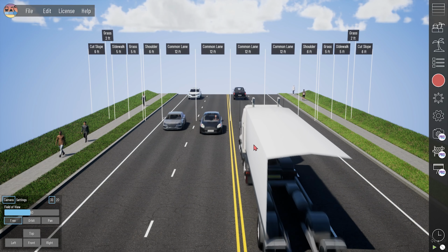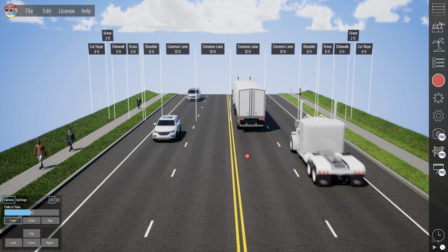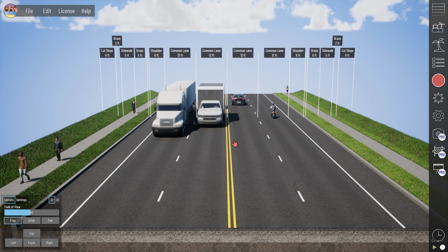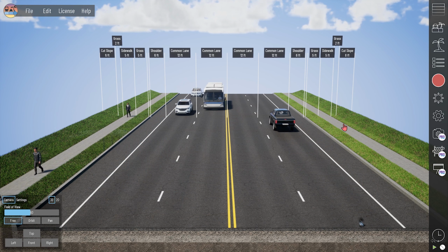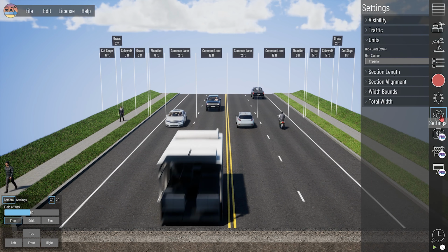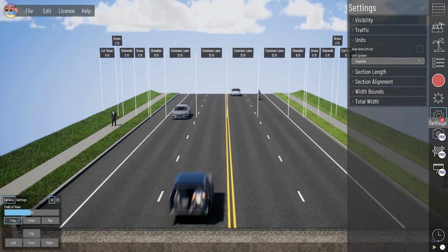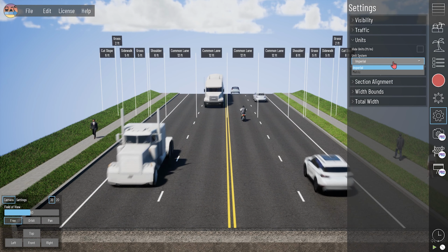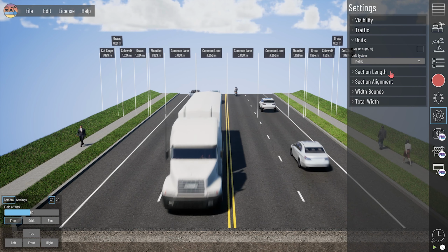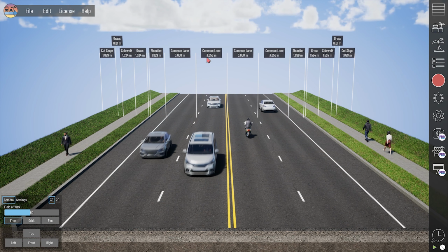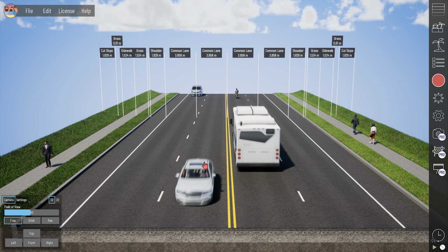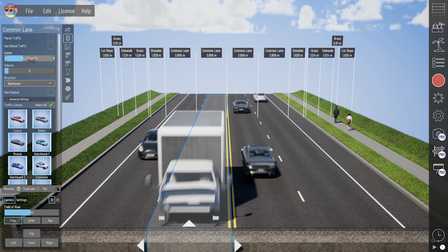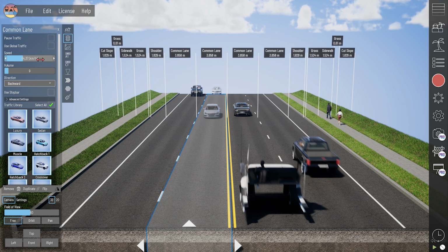Beyond Typicals was made in the USA, so it comes with default settings and objects which adhere more toward United States infrastructure standards. However, international users can utilize the application's customization features to adapt it for their visualizations as well. For starters, you can change the units from imperial to metric with a global setting change. Changing this automatically modifies the section labels, width and height inputs, traffic speed inputs, and other units of measurement throughout the software.